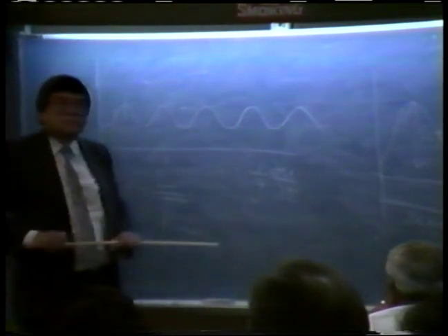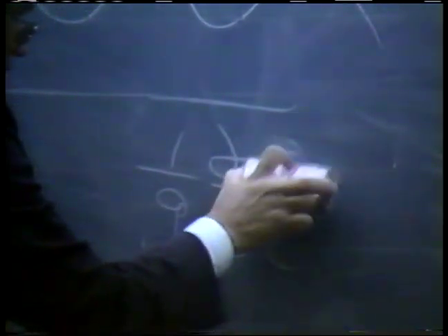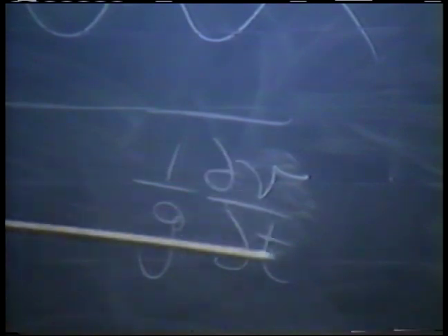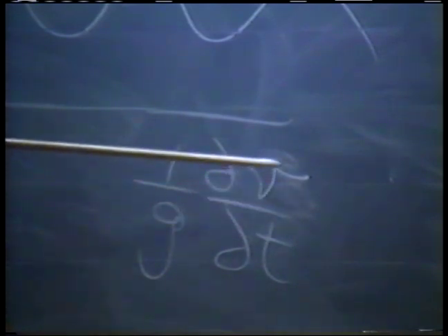And du dt, you would agree with me that u doesn't vary too much. Let's say, well, I'm using u in here when I should have used v. Let's be consistent here. V is the mean velocity of the flow. You would agree with me it cannot vary too much. It could vary from 3 feet per second to about 12, 15, perhaps 18 feet per second. It varies within less than 1 order of magnitude. But because we're taking the rate of change with respect to time, and since this is such a slow-moving wave, then this becomes a very small term. And if furthermore you divide that by 32.2, then it becomes much smaller than everything else that we could care to put in there.